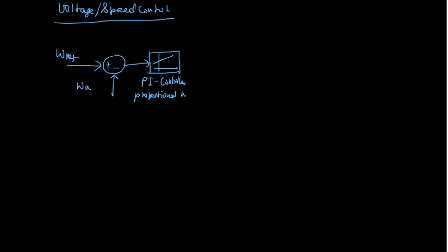Proportional integral controller. Okay, done. And then again the duty ratio limiter will be there, because at the end we are going to realize or apply the voltage delta VDC by 2 with respect to what? Through what? By changing the duty ratio of the switch.